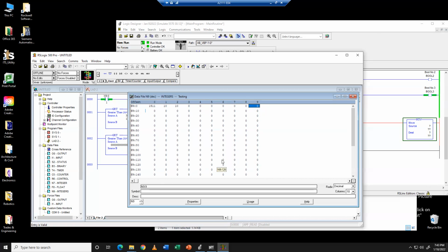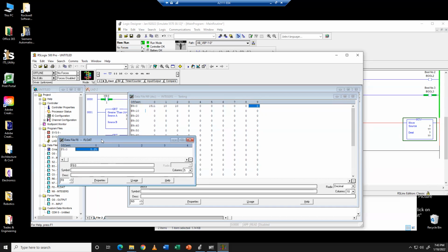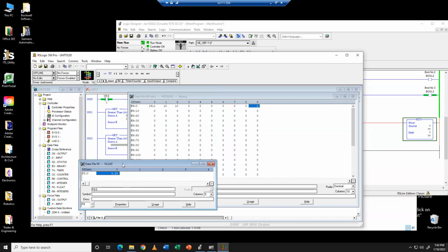If you're going to need to use decimal places, so let's say you've got a flow meter and something runs at 1.45 liters per second, you'd actually need to define a floating value for here. A floating value, you can't actually get to the bit level information of it. You can only view its whole value. Does that answer your question?